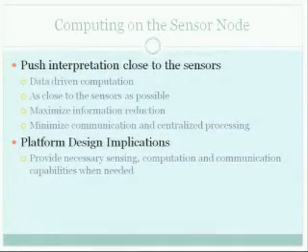And basically what we're trying to do is push the computation as low as possible to the actual sensors. As long as information is detected at the sensor node level, we want the sensor node itself to summarize and interpret this information as soon as possible. By doing that, we will maximize the information reduction at the sensor node level, and minimize the communication at the network level.